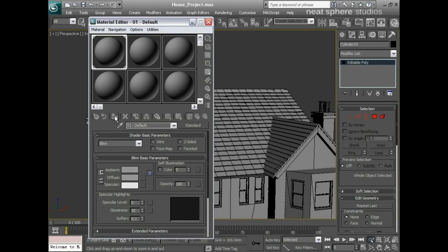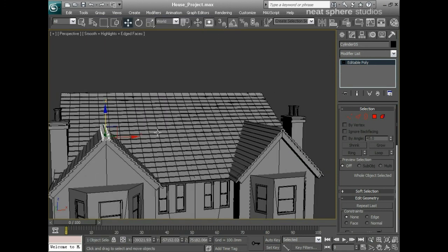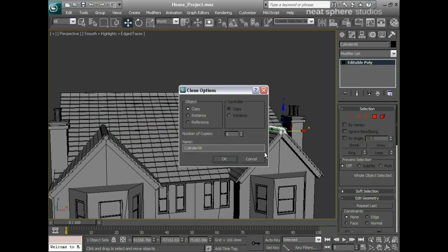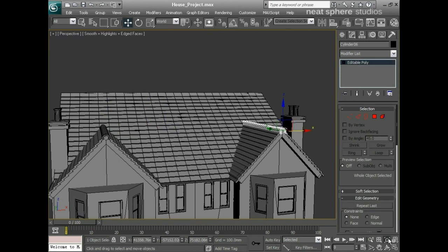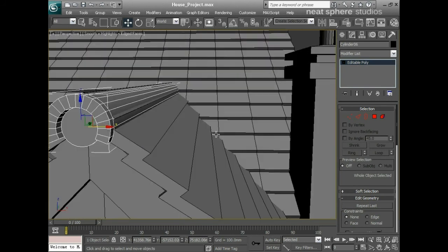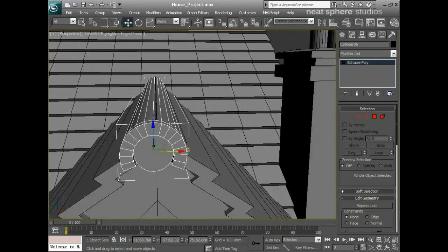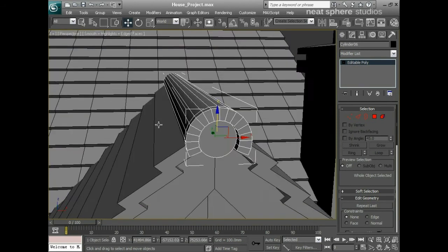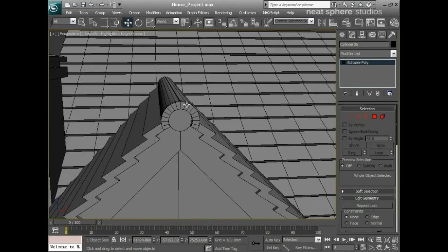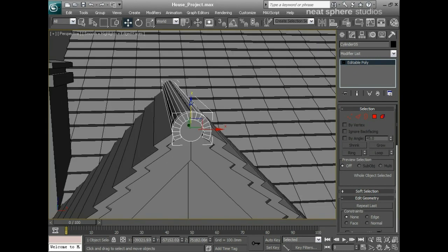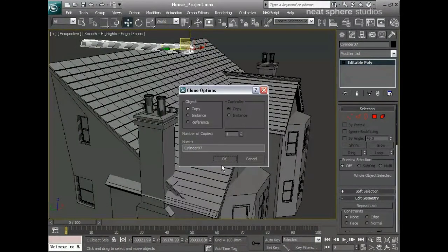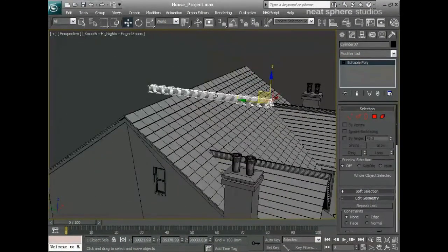Okay, materials editor, chuck a material onto that. And we'll pull this across here. Okay, that's good. So I'll just realign that properly. Maybe pull it up fractionally. And because of that, I will double check this one. Yeah, that needs to come up just slightly as well. Okay, so I'm going to make a copy of this object. And I'm going to rotate it through 90 degrees.